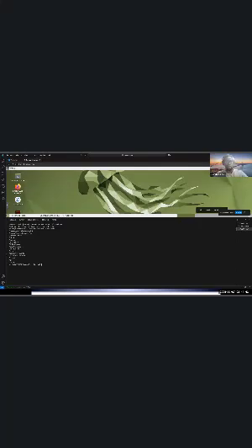Like I said, you can also remap your topics. There are different ways of doing that. You do that when you're writing the LiDAR scan code, in the robot description for the LiDAR sensor. You remap the scan topic. So what we're going to do is echo the LiDAR scan: ros2 topic echo slash lidar slash scan. When I try it, it's going to give us some messages. We're going to see the messages now.